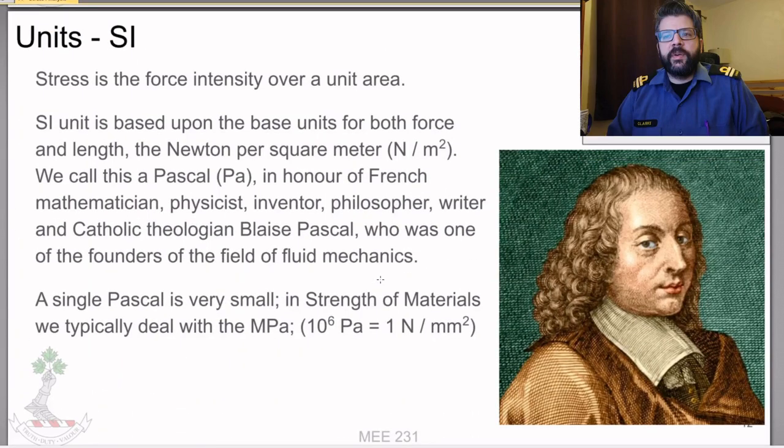So, talking about units in the SI system. Stress in general is the force intensity over unit area. So in SI, we're working with a Newton per square meter. Those are the base units for force and length. So we're working with newtons per meter squared, and we have a unit for that. We call that the Pascal, in honor of this guy, who was one of the founders of the field of fluid mechanics. He's the one who invented the hydraulic press and a whole bunch of other things.